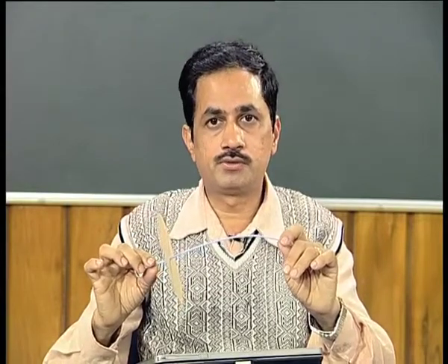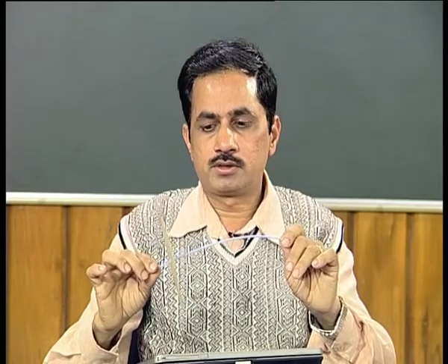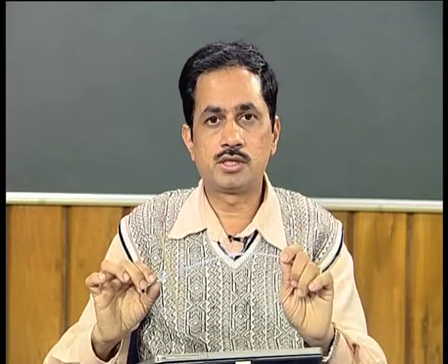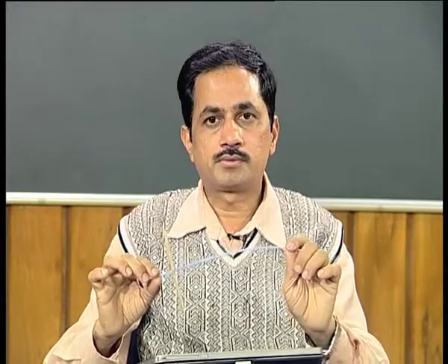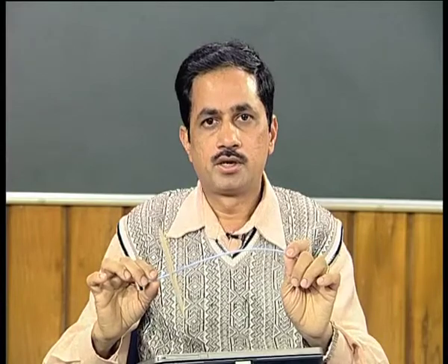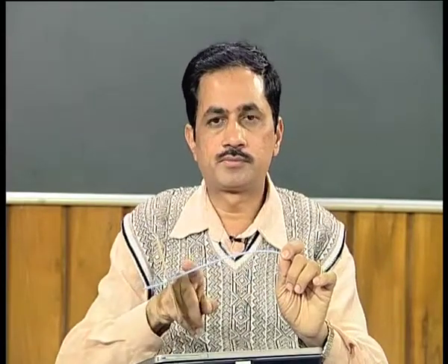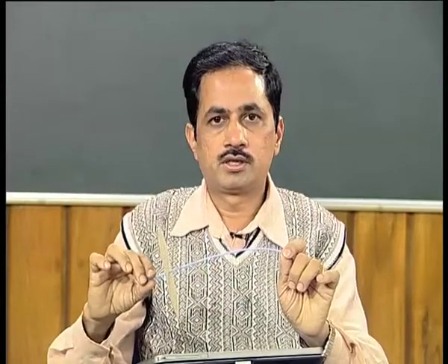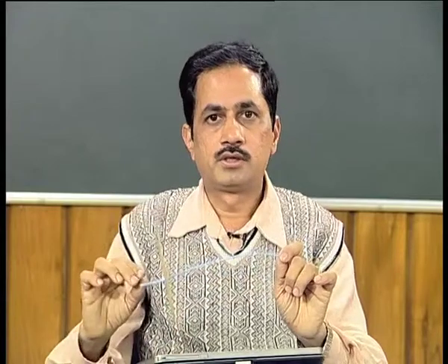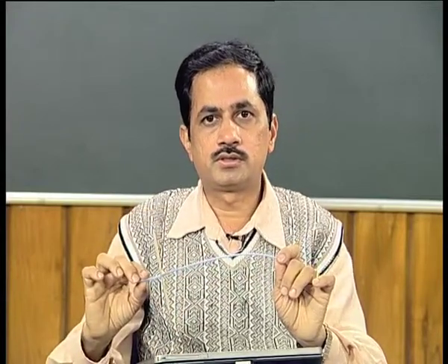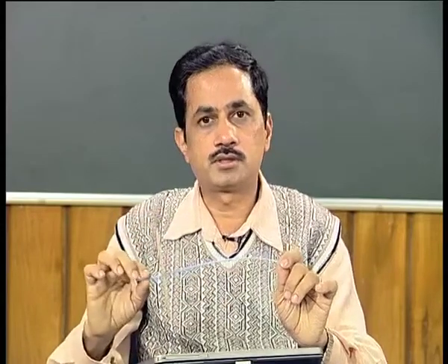So, this will be a free vibration analysis, and in this particular case synchronous motion is not there. In the previous case we considered that, and we saw that when this shaft bends and whirls in synchronous condition, the fibers of this shaft which are in tension always remain in tension, and those which are in compression remain in compression.